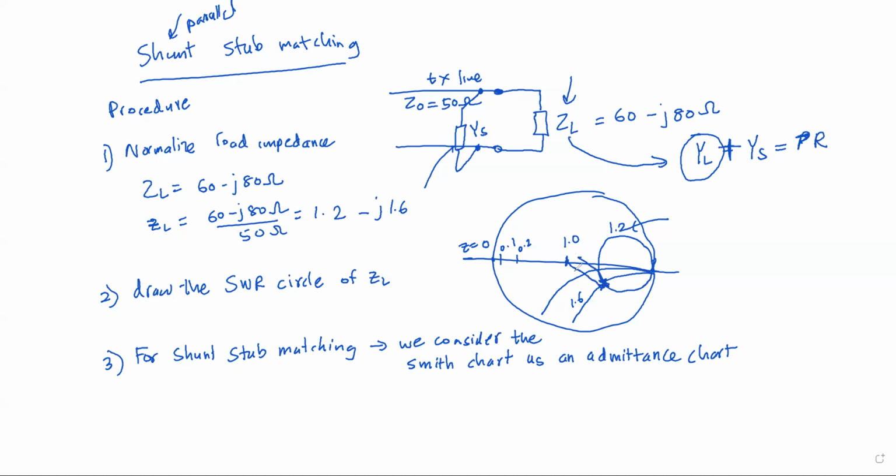I can't draw this correctly, but the point which is 180 degrees opposite to this impedance will give you the admittance point of that impedance. Once you take the ruler, you can take the opposite point on the other side of the Smith chart, going across the 1.0 point. Can you understand what I'm saying?